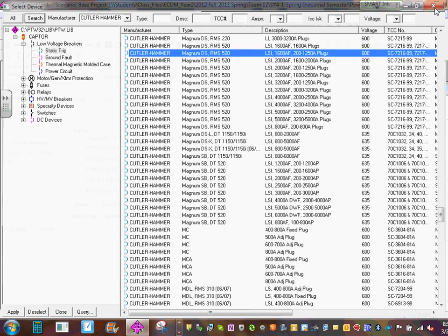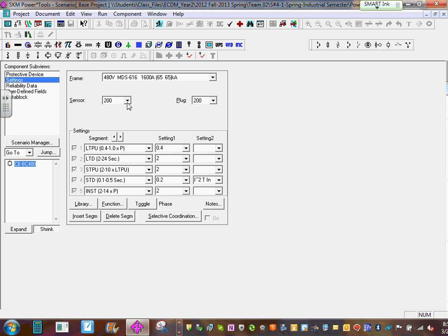Now you load it in your system. Now let's go make it, what did we say we're going to make it? 1000? Go grab 1000, make sure it's 1000, and can you guys see the long time pickup is set at 4? Or go all the way to 1. So change 1000, 1001. Oh, okay, let's go back a second here.